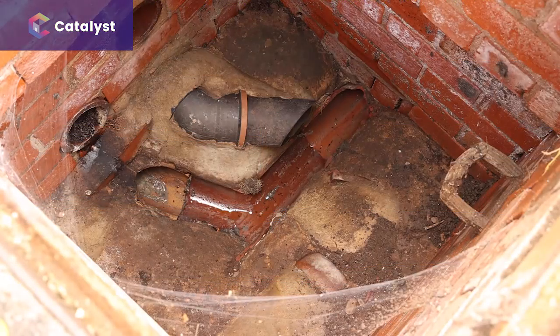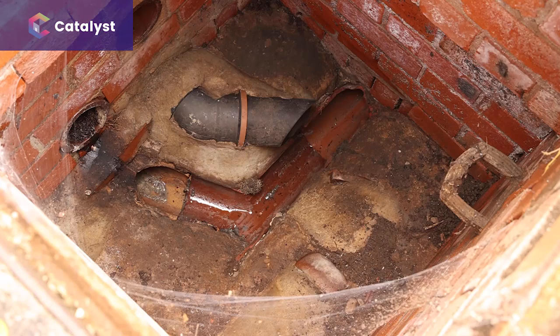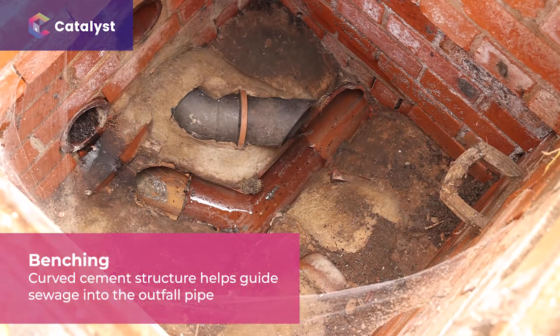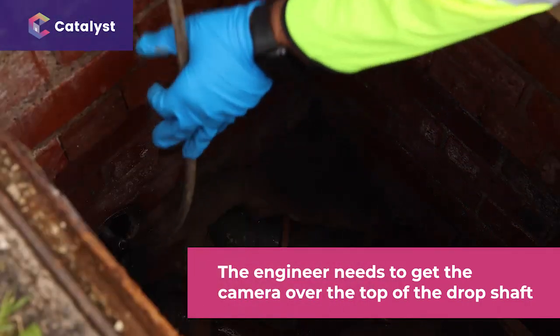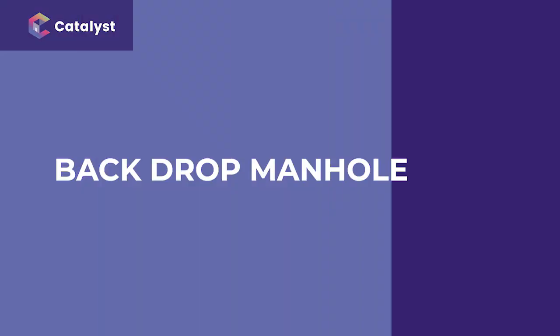The manhole has two backdrop shafts entering it. These are consistent with the drainage engineer's initial assessment of the drainage system. You'll notice one drop shaft appears to have been repaired at some point because it has a plastic pipe that comes over the top of the benching. Benching, by the way, is the curved cement structure that helps guide sewage into the outfall pipe. The engineer needs to get the camera over the top of the drop shaft to view the upstream pipe. First, though, let's look at what a backdrop manhole is and why it's used.